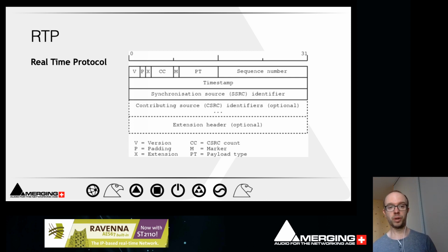So this is a really big difference compared to ATM networks, for instance, or even just plain numeric digital connections, AES or MADI. And this is using the RTP protocol that was issued in the 90s, and that is using two things: the sequence number, that is the number of the packets, so that the device can restore the proper order of the packets, and the timestamps.